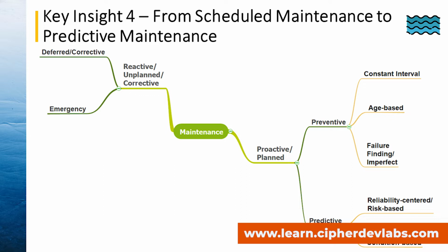Then we have emergency maintenance. It is also known as breakdown maintenance. So that's basically the maintenance required when an asset or a piece of equipment suffers from an unexpected breakdown or change in condition that results in an immediate threat to the health and safety of the equipment. This type of maintenance we must avoid as much as possible, because this will result in the entire production process coming to a grinding halt unless the issue is fixed, because production cannot move forward unless these issues are fixed.